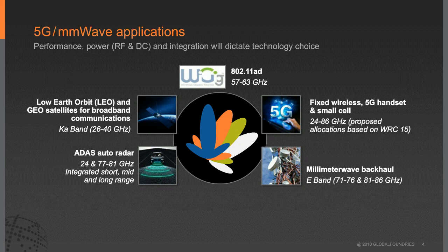Some of the key benefits of using phased array for these applications are to focus the beam, which allows spatial multiplexing, where the beam that is being broadcasted is a very narrow beam and is targeted to a single user. As we go to millimeter wave, the antenna dimension shrinks. We can put a lot of antenna elements in the phased arrays, which allows for spatial multiplexing. The power levels transmitted by each antenna element is reduced dramatically.